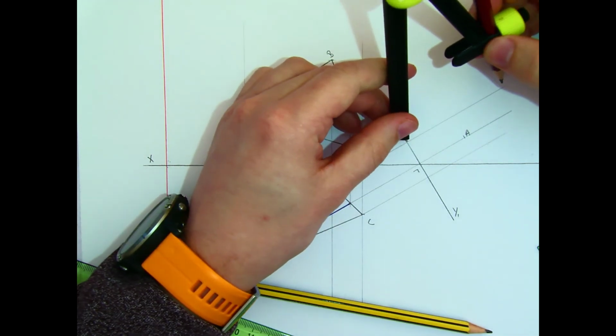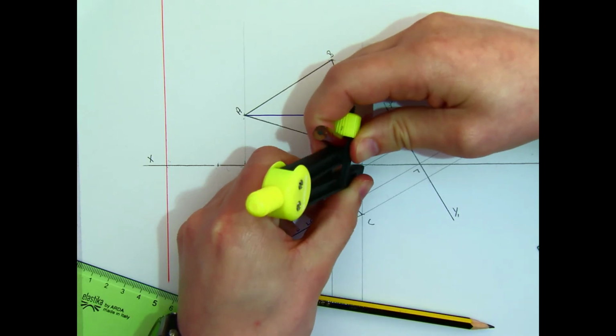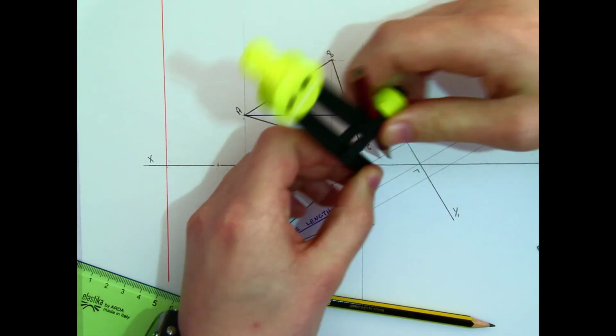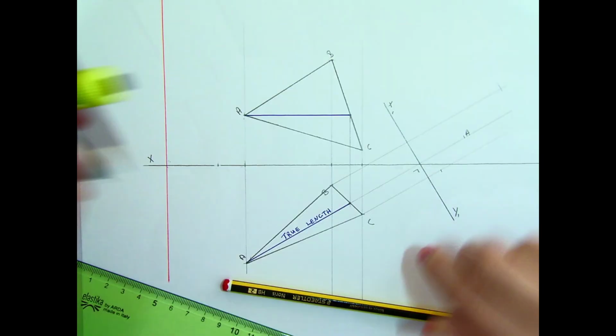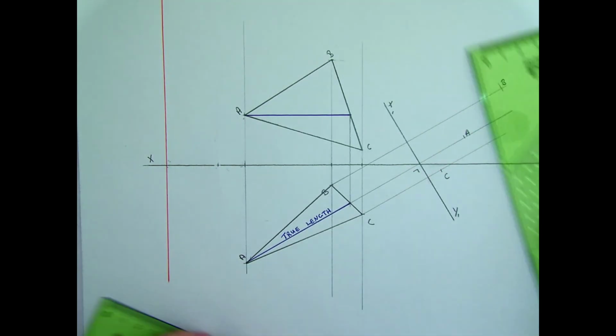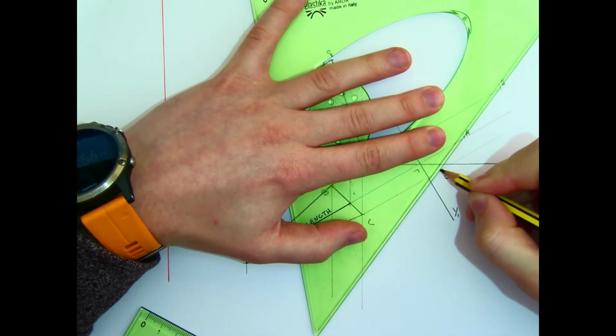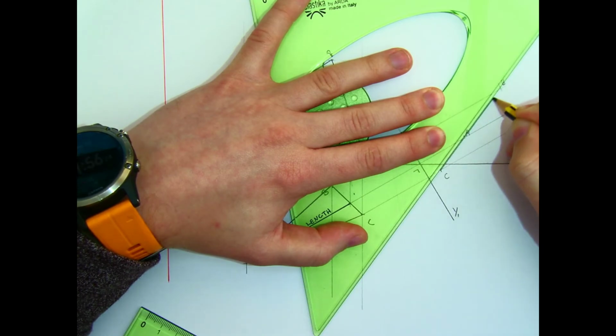So it's an altitude of 63, and C then also, which had an altitude of 9, is marked down here. So this is B and point C down here. Now each of these lines should then join up and form a single line. So this gives me an edge view of that surface.